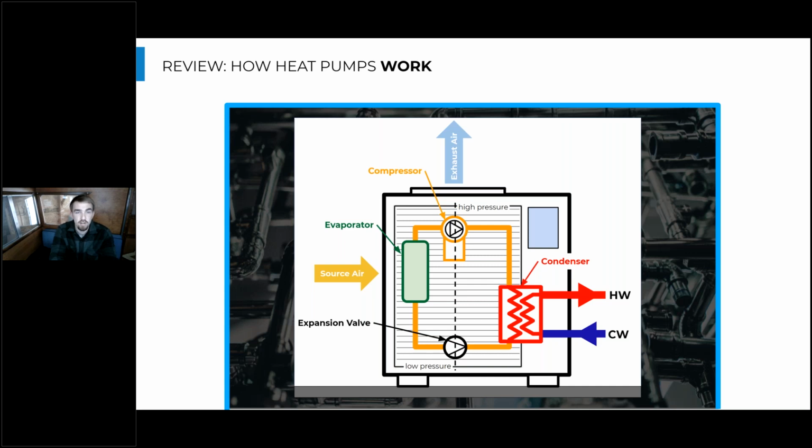There's different types of heat pump technology that operates with VRF, whether it's just changing the compressor speed or having several different circuits that handle different quantities of refrigerant depending on the conditions they operate in. So that's a great way for this equipment to operate most efficiently and only push as much refrigerant as necessary to accommodate the load that it needs to.